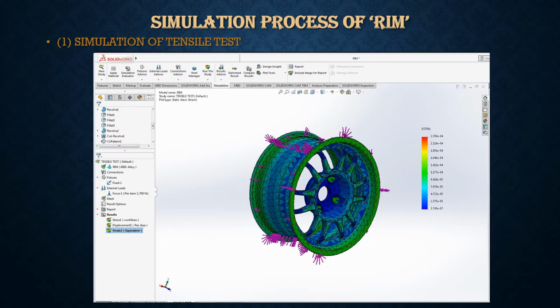First is the simulation process of the rim. First simulation is about the tensile test. As we can see, this one is the final result that I get. For the steps, I start with simulation. Second one is new study, then click static, and then select material.